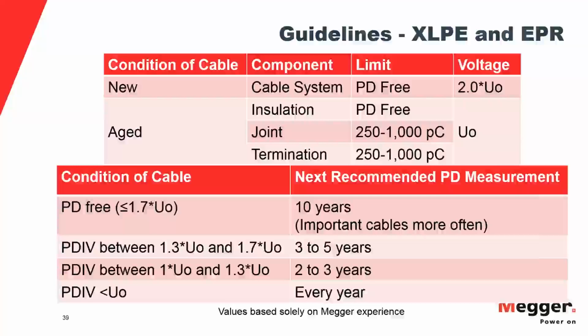Why can't you fine-tune the DAC to have 60 hertz frequency or very close? The technical reason is that inside the equipment there's a fixed inductor. To get to exactly 60 hertz, you'd have to match the inductor and the capacitance of the cable exactly. That's not really practical, to have a tunable inductor to match every cable. So we take an inductor that's suitable for a range, and the frequency then depends on the length of the cable.